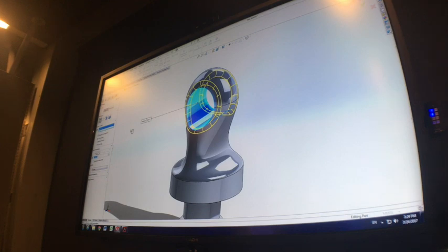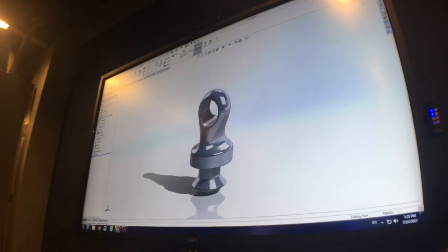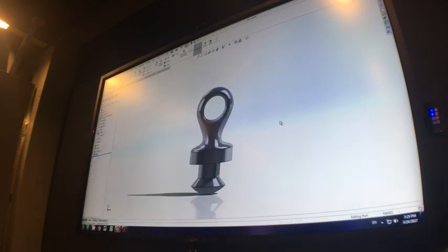If I wanted to see what other sizes I could go to, I could just keep increasing that size. Okay, 1.5 works, 1.6, 1.7. Actually, I might have crashed it. But eventually you get to a point where the preview no longer works, and then you know you've reached your limit for that fillet size. And you can see that 1.8 doesn't work. All right, so stick it back to 1 and press OK. And that part is finished.